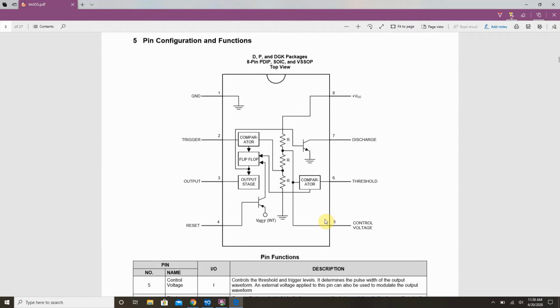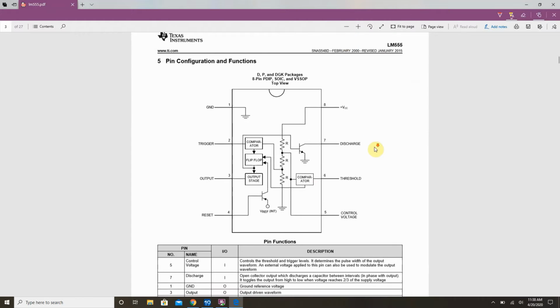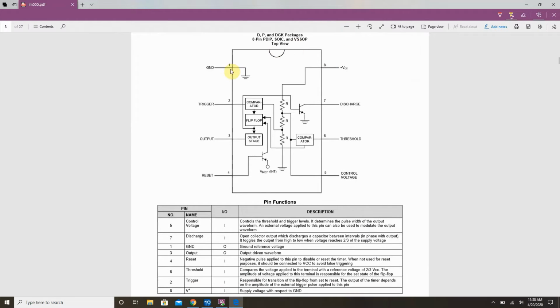All right, this page here is probably one of the most important. This tells us our entire pinout for this chip. You learned this when you did the soldering project. In a U shape, it's 1, 2, 3, 4, 5, 6, 7, 8. U shape, just like this, giving you the U shape. Has that little notch at the top. That's how you know which one's which.